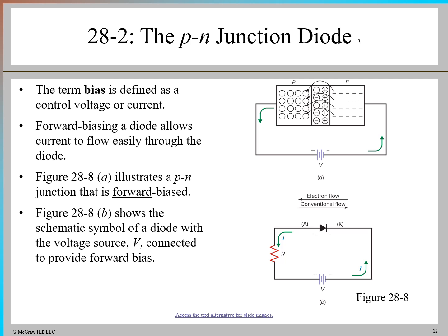When the voltage is sufficient, it repels free electrons from the n side across the depletion zone and into the p side, where they recombine with holes. The electron flow on the p side moves toward the positive terminal of the voltage source, completing the circuit. For silicon diodes, this process requires a minimum of 0.7 volts. A resistor is typically added to limit the current.